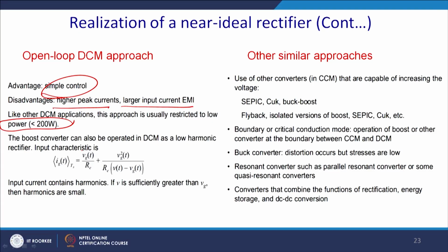So, all can have an inverter fed drive, and thus we are required to rectify and place a PWM converter in between to give a processed DC to the inverter and thus a processed AC at the output, and also you do not throw any garbage in terms of power quality to the utility. So, let us come back again, this is the application part of it.